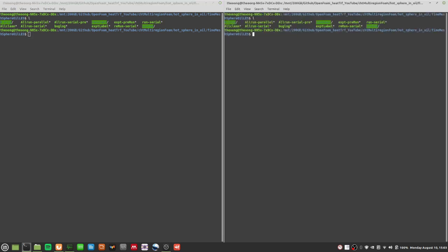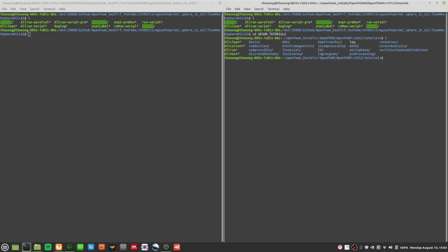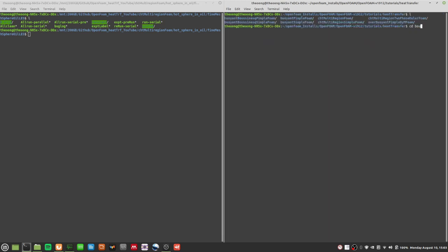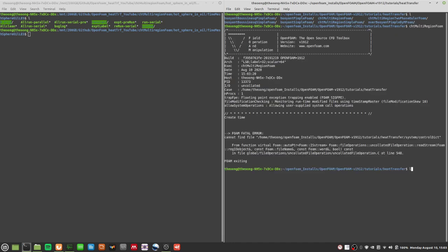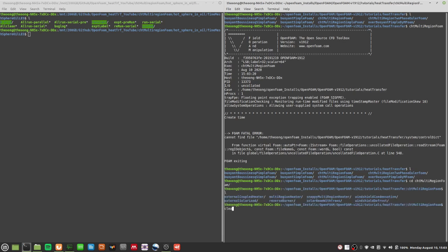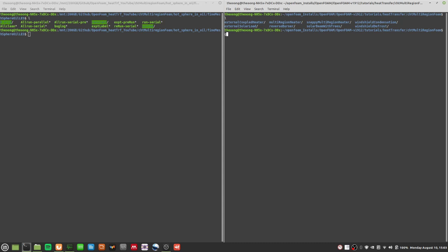Okay, so as with any case where I want to do turbulence models, I'll go to the foam tutorials just for reference, and I will go to buoyantPimpleFoam or chtMultiRegionFoam, for example. cd chtMultiRegionFoam, and I will grep -r, which is to find turbulence models.